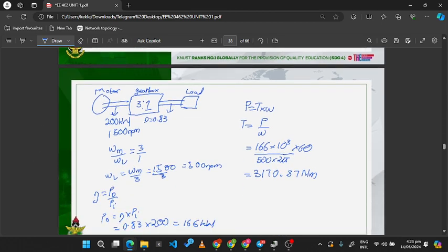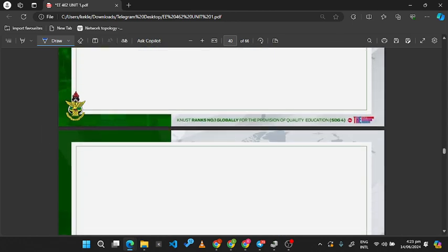Okay. So we've seen omega is inversely proportional to flux. So if we want our omega now to be 2 times omega rated, then the flux would have to reduce by that same factor. So our phi now will be 0.5, right?